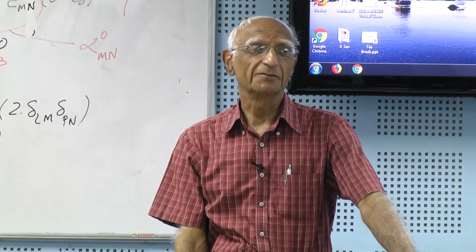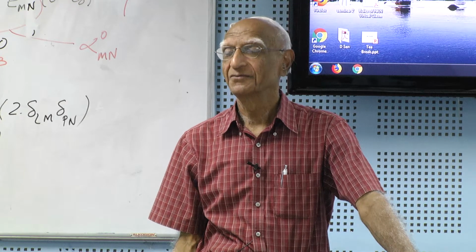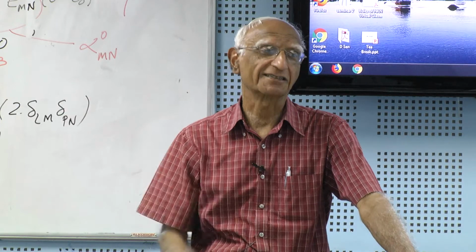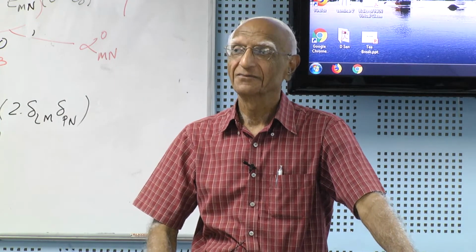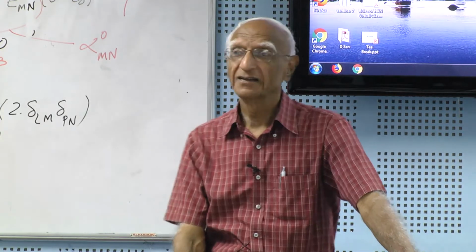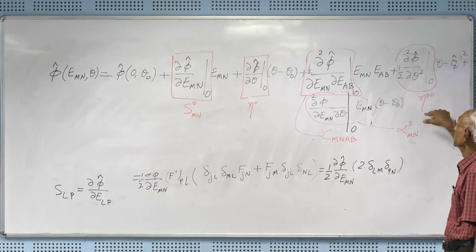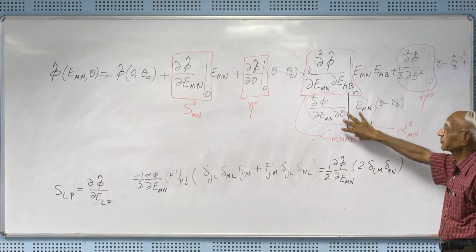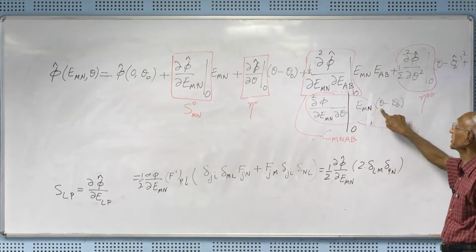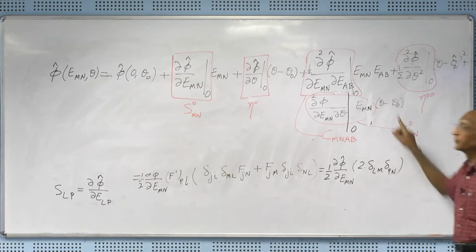Good luck in finding them from experimental data. So that's where the difficulty comes. Now, how do I find these 21 constants? I can't. It's difficult. And then this is for the second derivative, and this one is for thermal coefficients of expansion, because they are going to multiply these two terms. And when I differentiate, this will give you thermal stresses.